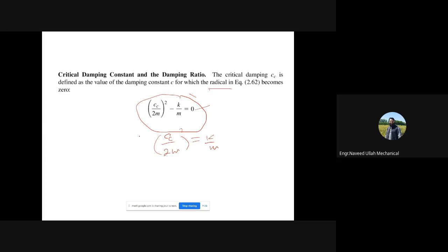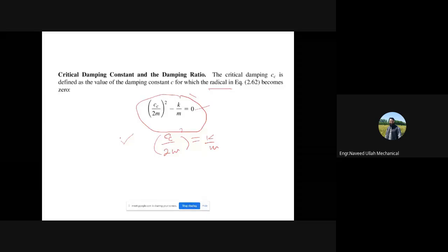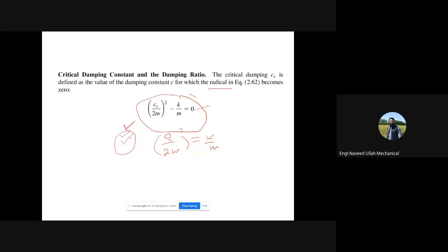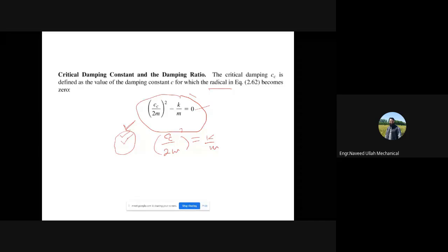We will discuss what a critically damped system actually is. You disturb the system, and the spring takes or stores that kinetic energy and dissipates it. If it dissipates that kinetic energy in minimum time and takes the equilibrium position in minimum time, then the damping present there is known as critical damping. So the ideal damping is critical damping. You disturb the system and it regains its equilibrium in minimum time, so we call it a critically damped system. But it depends on the designer.